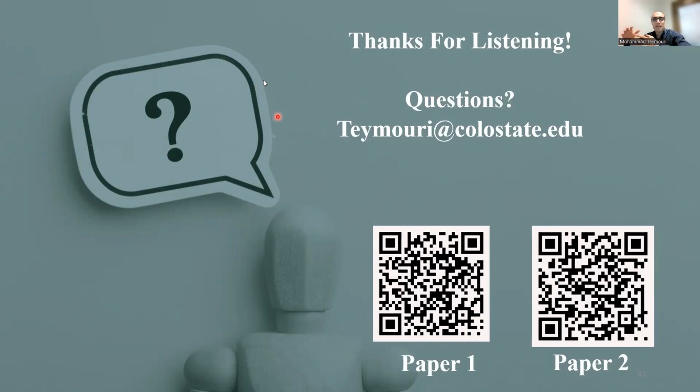I want to see that the pH reduced, and then focus only on the chloride behavior or chloride content in the samples. But you are right that CO2 injection is a big deal. Maybe it has some advantages, but we need to take into consideration that when we have CO2 and also calcium hydroxide in the matrix, we probably have a very dilute acid that can impact the pH. It probably prevents chloride binding, which is not good regarding chloride-induced corrosion. But that's a good question.